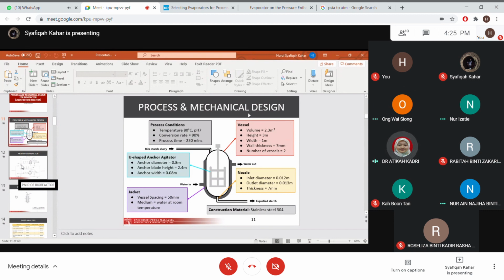So do you refer to any standard when you design your agitating unit? I did not refer, because I really can't search any related. I would suggest you to go and find information on designing an agitation unit vessel. I'm sure you can find common or generic ratios, in terms of the diameter of the impeller, the diameter of the tank, and the height of the liquid.